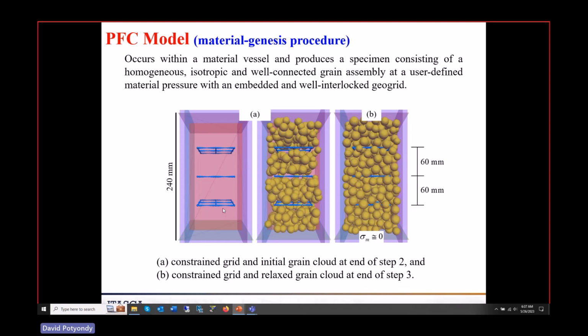Then you lay on a geogrid and let that sit under gravity. Then you throw in more aggregate on top and let the whole system come to equilibrium. Just keep doing that. Then you compact it on top with a bunch of vibration. They run these big machines and compact each layer. You could directly model that in a discrete element model, and that would be the best possible way to model it.